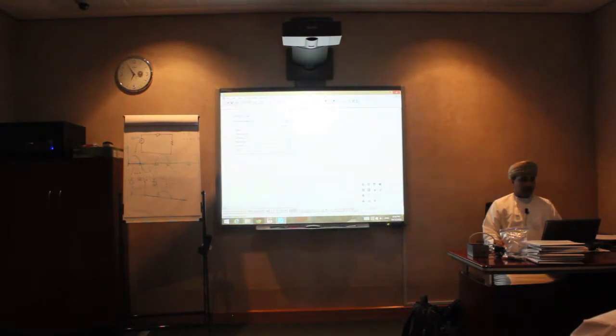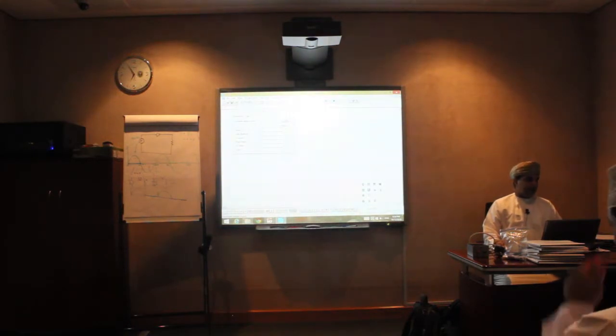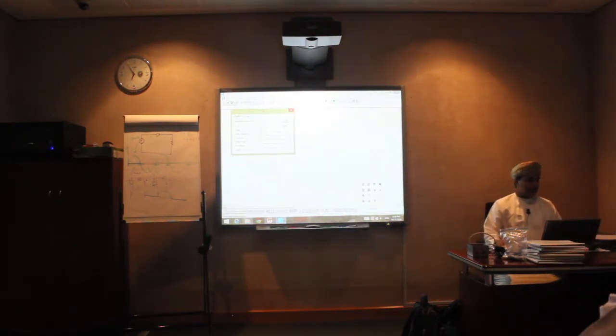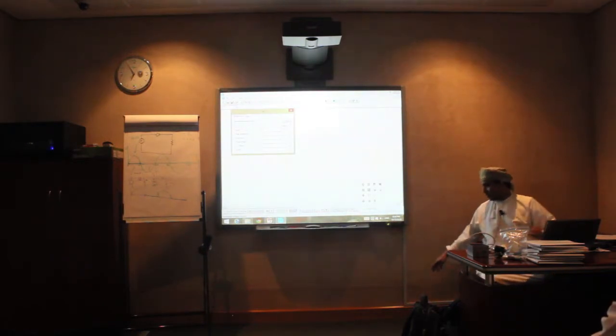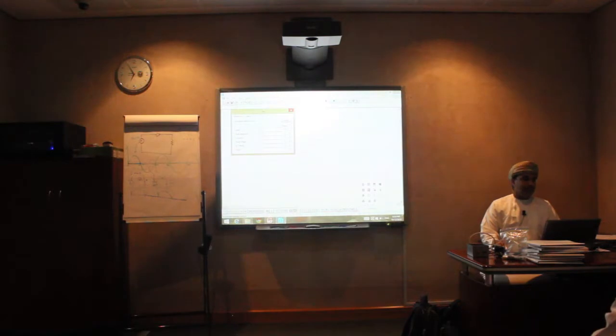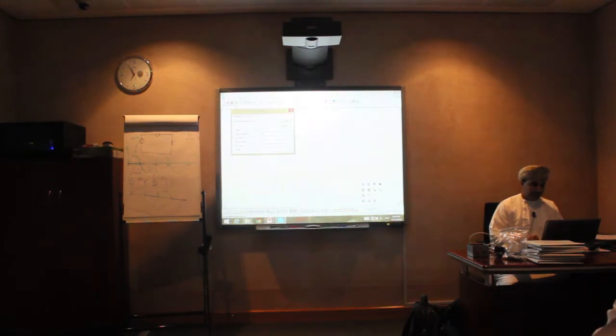Now you can put, for example, the value of the voltages which you would like. So open this one, and in this window here, which is the sine one, you can name the source. For example, you can call it VS, V source, whatever you like. And then the value of the voltage in peak. If I assume the value of this voltage source is 240, this is an RMS, right? So the peak is 240 multiplied by square root of 2, which is equal to 340, right? And the frequency is 50 Hertz.